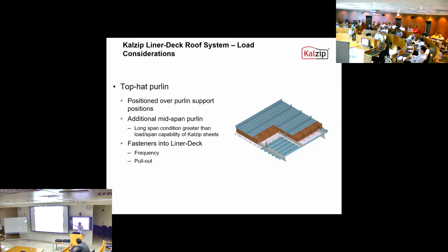So this could be around the edge of the building where you need to put the supports at closer centres. Then when you go inboard where the loads reduce, you can maybe omit. Sorry? This is just a riveted or self-drill fastener to the sheet.